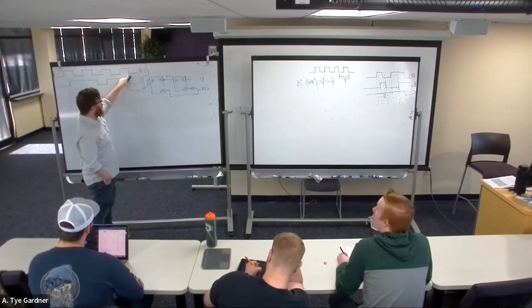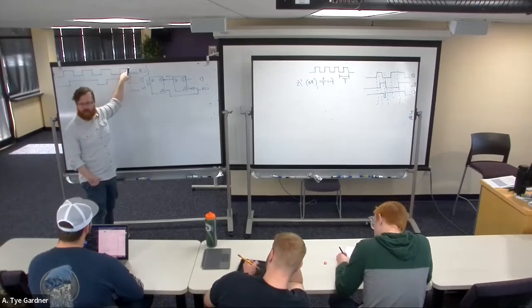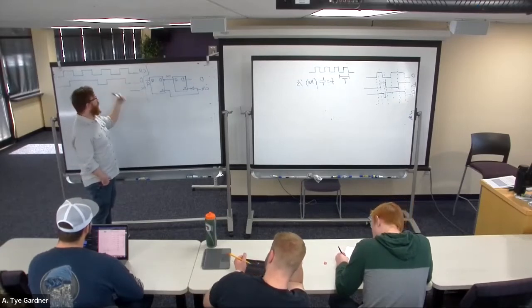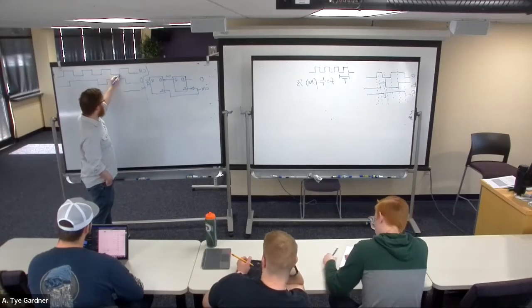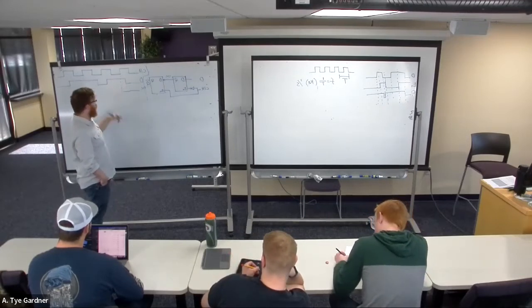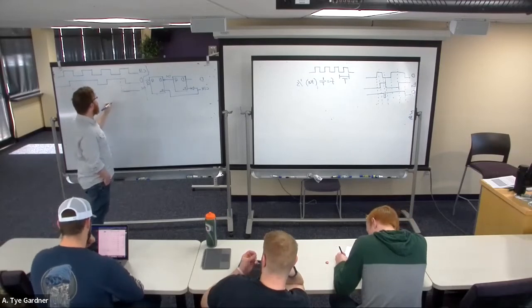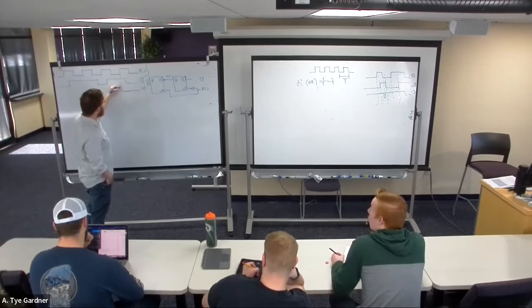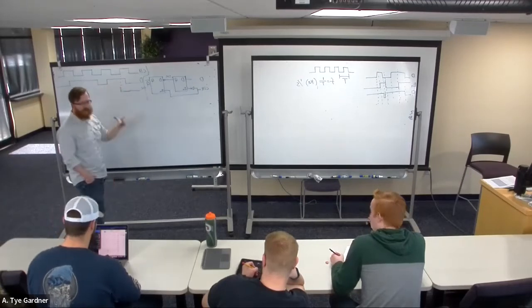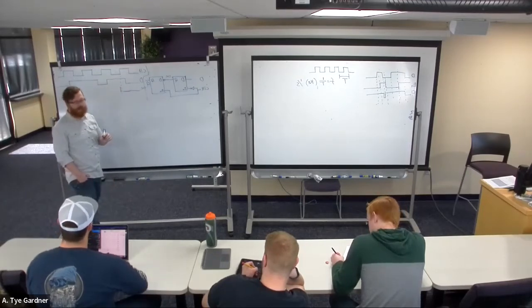And then because clock goes high, which is our enable signal that gets inverted, it can no longer follow. So nothing happens. In fact, nothing can happen on that line until here when we turn back on our enable, at which point D is high, so it can step up. And I'm going to use a little bit of a delay just to offset it because it's going to help us visualize things in a second.